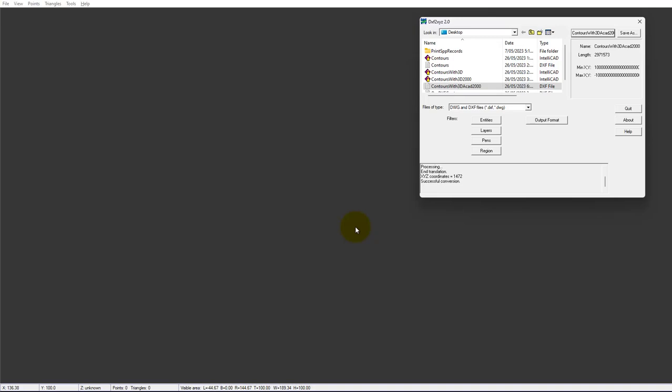So I've got all the coordinates now in one file, but TinMaker that we're going to use next needs the extension TXT. I'm using Windows 11 here, so I've got to make sure using the view and the drop down that I show the full file name, and I'll need to rename that .txt.